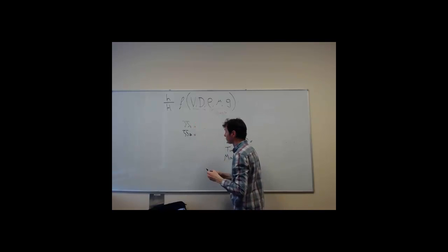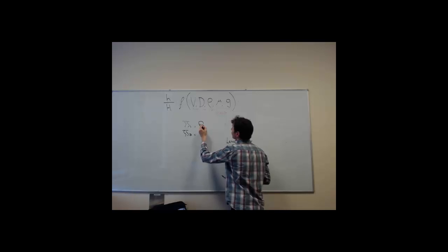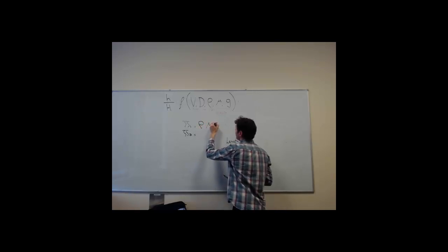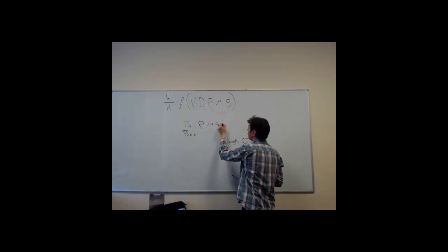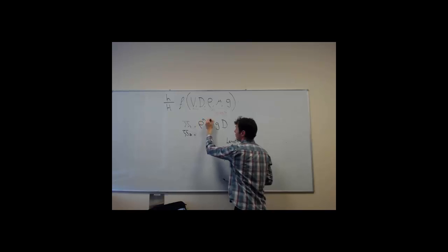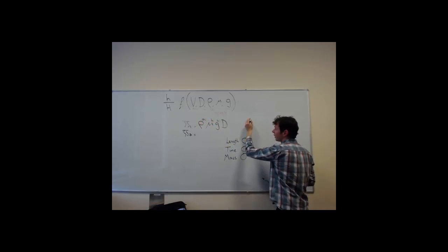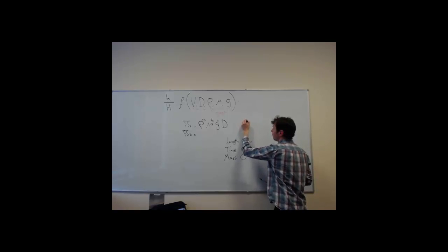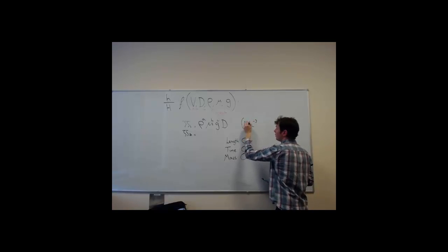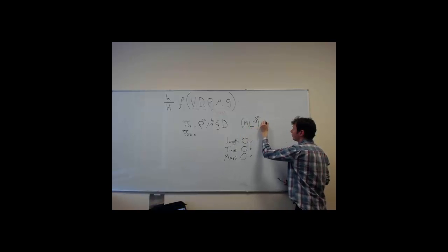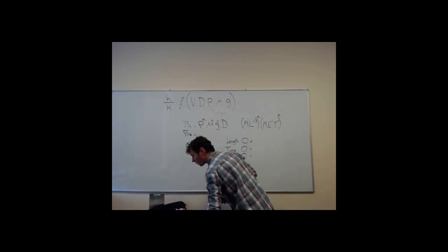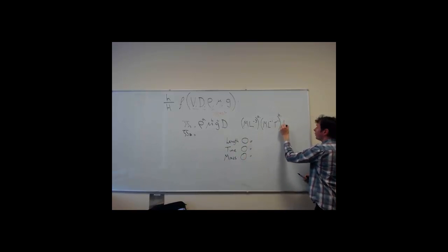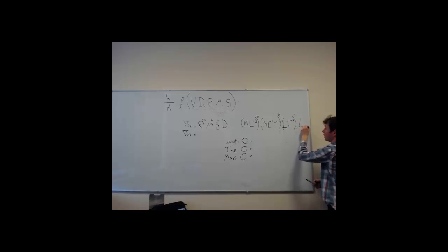So now we've got rho, u, g, and d. Okay, so we're going to raise these to powers a1, b1, c1. Write this out in full. So we have for our Pi1 group, we've got mass, length minus 3, density to the a1, velocity, length times time to the minus 1 to the b1, g, length times time to the minus 2 to the c1, and then d, diameter is just length again. Okay?